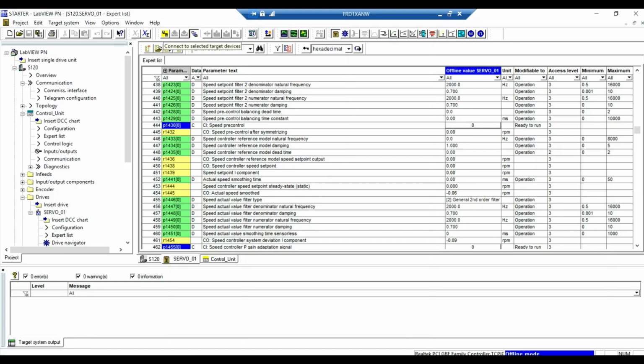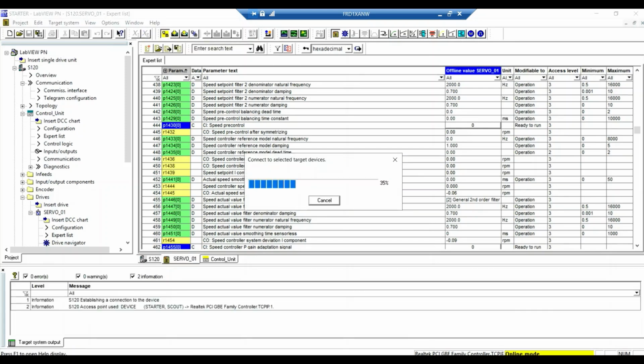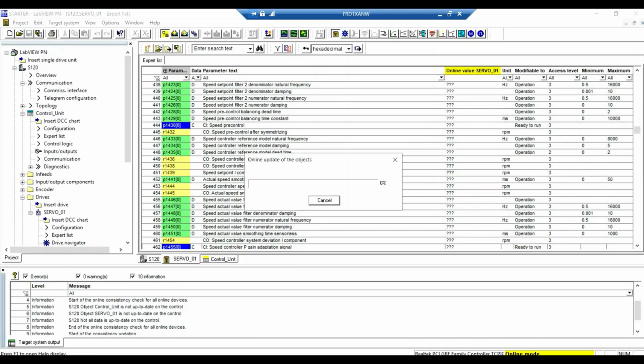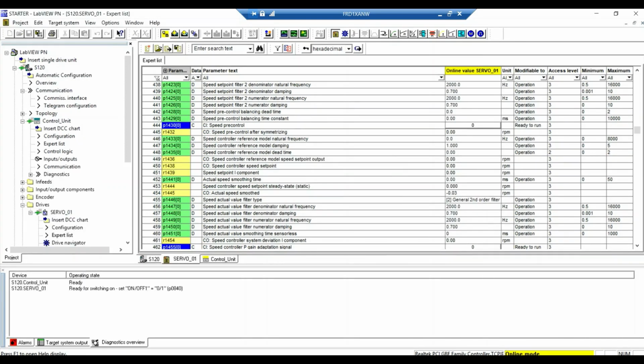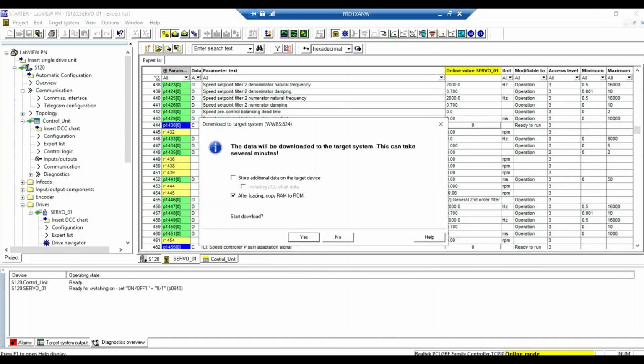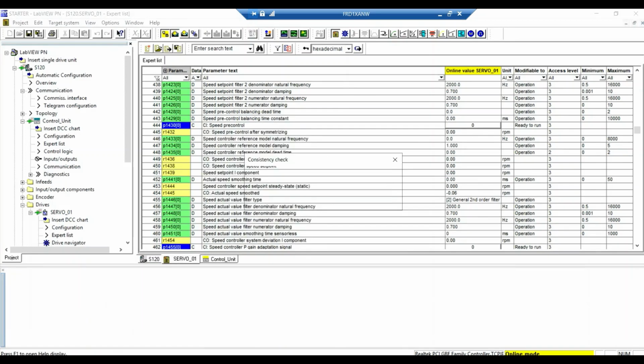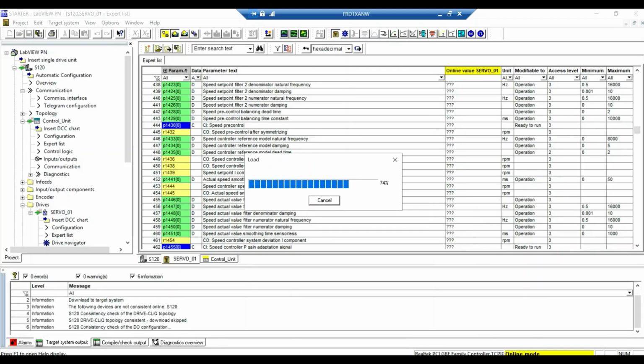After the control unit and servo drive have been configured, you need to add in the expert list all the functions used for communication and command. The control unit has detected the connected motor module and the SMI motor during the automatic configuration process. The device data have been transferred to the control unit. The control unit has automatically entered the correct device data into the parameters required to operate the components. The sample project is now ready to commission.